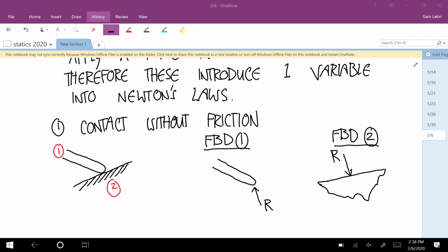So we decided that there's a force perpendicular because it limits that degree of freedom. What about the axis perpendicular to that? Can it move along that axis? Yeah, so there's no force along it, and there isn't one in that free body diagram. And what about changes of orientation? Can you rotate this thing? Yeah, and so there's no couple.